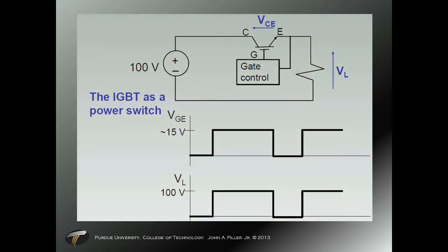So, with the IGBT in mind, we're going to use that as a control device. We can pulse width modulate, or PWM, the gate with the lower voltage, notice the 15 volts, to control a higher voltage on the output. So the voltage delta between G and E is the 15 volts. The voltage delta between C and E would be your VL. And so C and E turn on, for the lack of a better term, full on when you put 15 volts between VGE and VCE, then allow flow to happen.